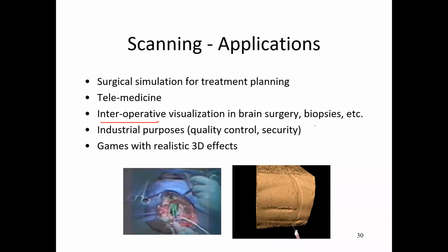Industrial purposes, quality control, security. Maybe you know that textile for defect detection, even the metal industry for defect detection, especially heavy equipment. You can't simply see the internal cracks of metals, so you have to use X-ray, right? But just by X-ray you can't do that. You have to use visualization. So X-ray plus some visual computing, you can analyze where the cracks are and so on, right?